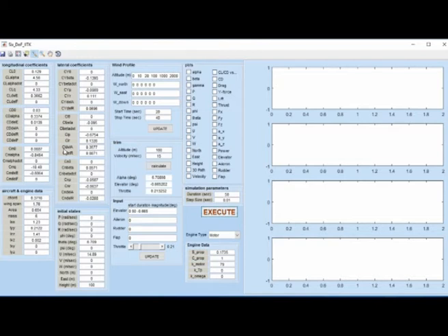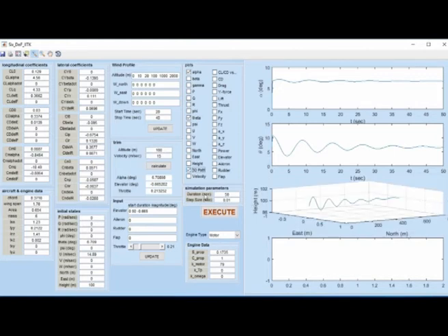If you want more accurate values, you can perform a wind tunnel test, then you can calculate all these aerodynamic coefficients. Now if I want to see the angle of attack, it will be plotted here. Pitching angle, you want to see this path in 3D space, the velocity, and whatever I select here, they will appear. The first 4 will appear here.